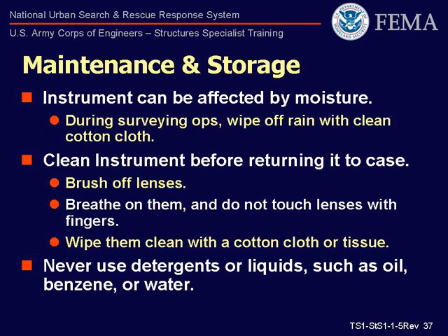During surveying operations, it is important to wipe rain off the instrument with a clean cotton cloth. The instrument should be totally clean before returning it to its case. This means brushing off the lenses with a soft cotton cloth, breathing on them, careful to never touch the lenses directly with your fingers. Never use liquids such as oil, benzene, water, or detergents to clean the instrument.